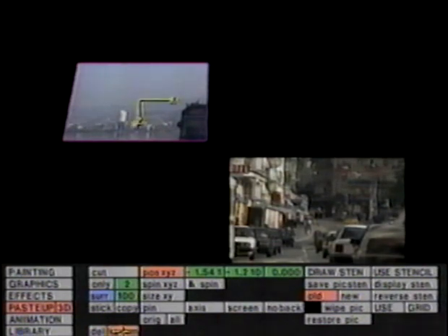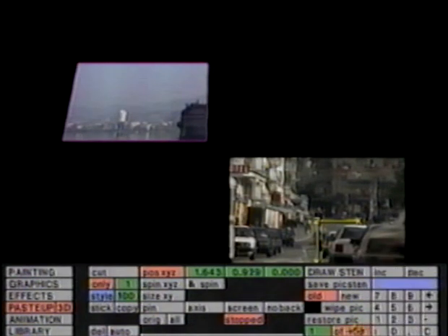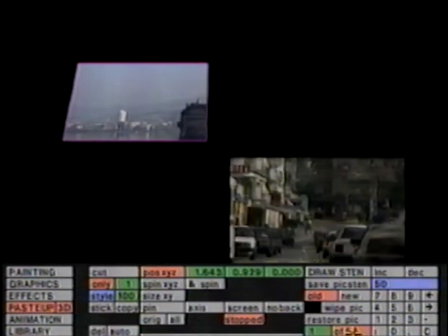Selecting Keyframe gives us access to a keyframe timeline. Keyframes can be entered onto the line manually or automatically. We'll set up the first layer with Manual Edit and the second layer with Automatic Edit. First we need to set the keyframe duration, say 50 frames.